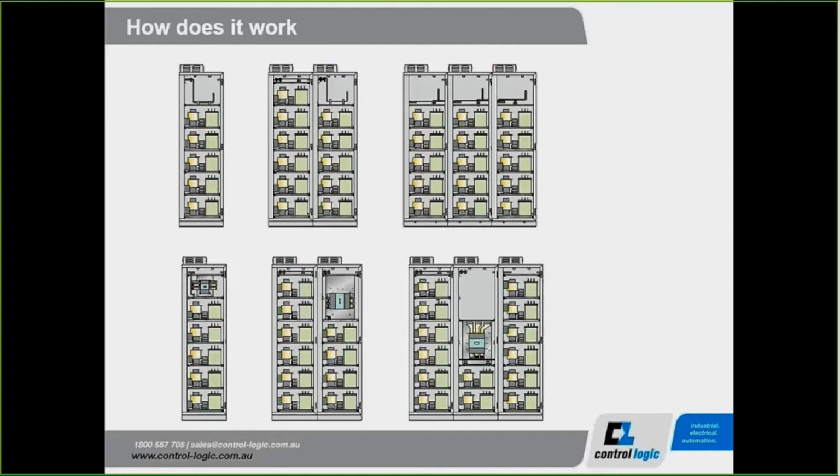Okay, so now let's go a little bit more in depth about how an actual power factor correction unit works. Well, I mentioned when you've got inductive loads, the current lags behind the voltage. So the way to compensate for that is to introduce some capacitance into the circuit, which can help correct it. Because when you have a purely capacitive load, your current actually leads your voltage, whereas with an inductive load, current is lagging behind voltage. So if you apply a set amount of capacitance to counteract the inductance, you will improve your power factor.